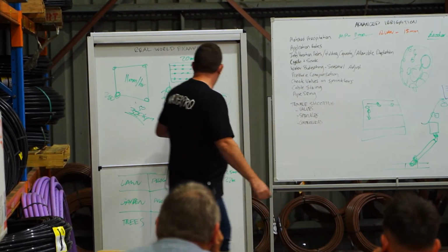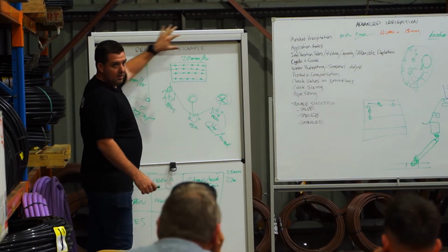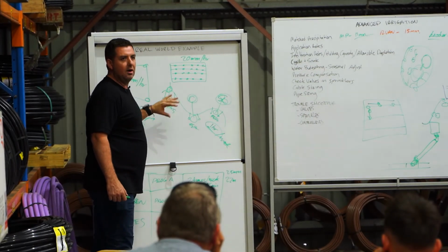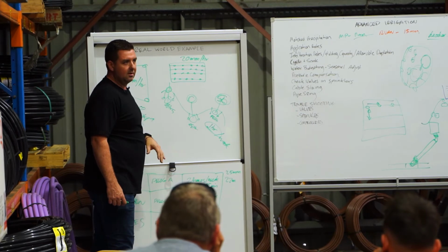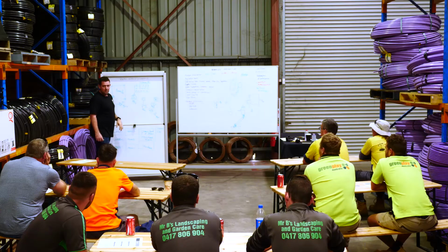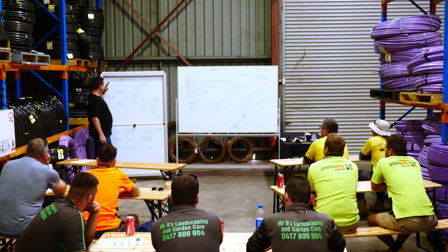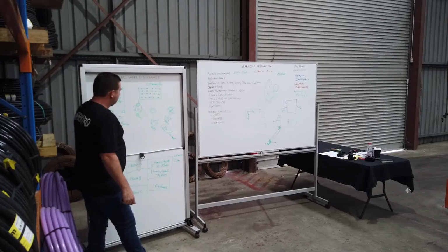There is nothing worse than putting all this in and then it doesn't work, and then you start walking around, you're like, what's going on? They're like, oh yeah, SA Water dropped the pressure the other day because the shower head kept blowing off. That's your fault. As much as it's not, it's going to be your problem. So keep in mind the pressure loss. Test it before you start.